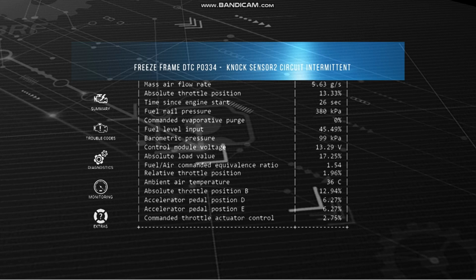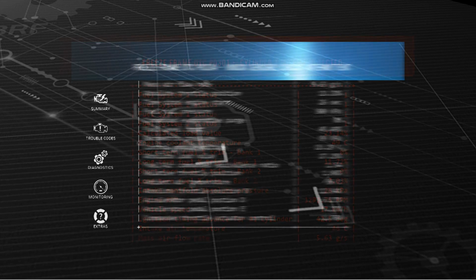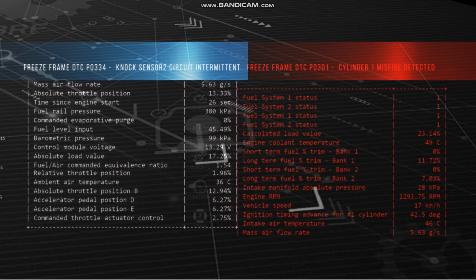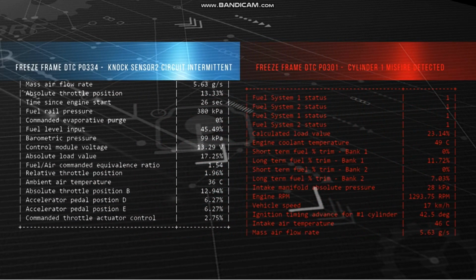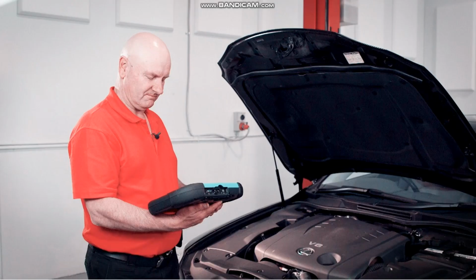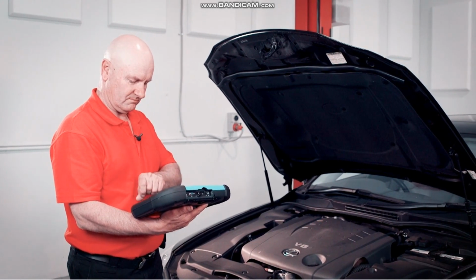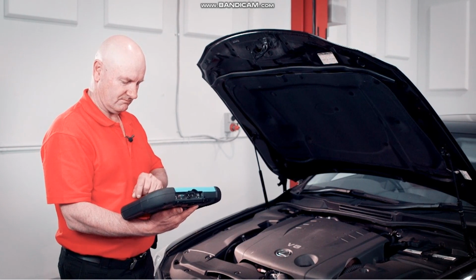Under OBD2, this data record may be overwritten if a higher priority code is reported. However, some OEMs allow for multiple freeze-frame data records to be stored, which is permitted under the standards. This data is often extremely useful in the diagnostic process to determine what actually triggered a particular fault code. Remember, when clearing fault codes via generic OBD Mode 4, the freeze-frame data record will also be cleared, with potentially valuable data lost.